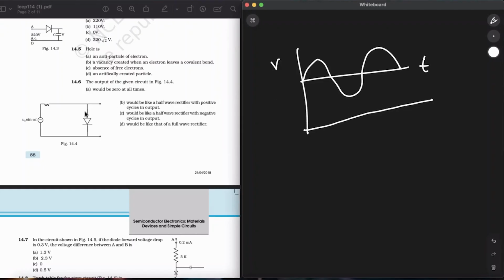What will happen is there's a diode, since there's a diode over here, it will just allow one part of this voltage to flow like this. Alright. During the half cycle, the diode will be forward biased, so it will let the current flow like this, just like the same concept we had done in the previous one. So when the diode is forward biased during the positive half cycle of input AC voltage, the resistance of the PN junction will be low and the current will pass through the circuit. The current that will be passing will be the maximum. So in this situation, the maximum potential difference, which will be VRMS under root 2, will appear across the resistance connected in series. So the result is zero output voltage across the PN junction.